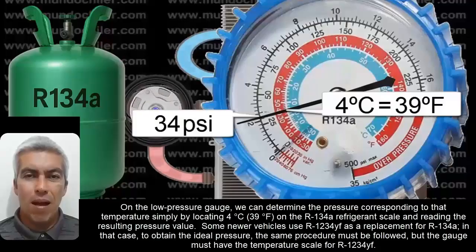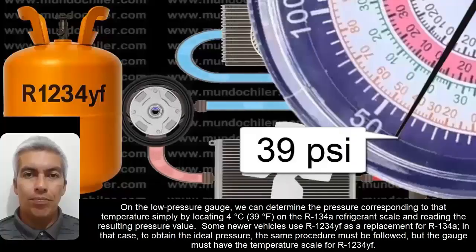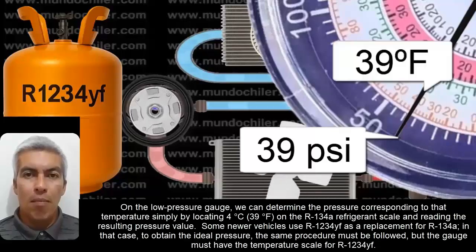Some newer vehicles use R1234YF as a replacement for R134A. In that case, to obtain the ideal pressure, the same procedure must be followed, but the gauge must have the temperature scale for R1234YF.